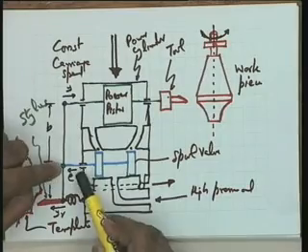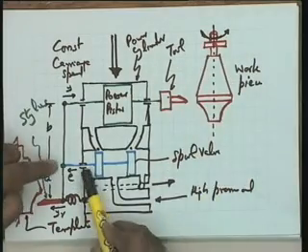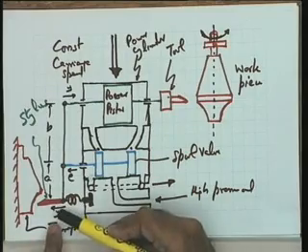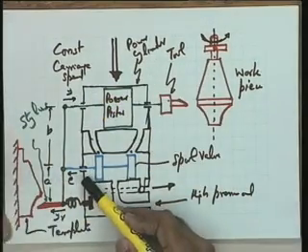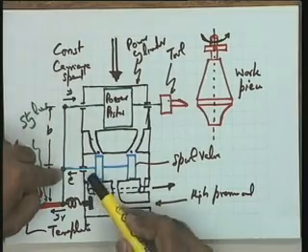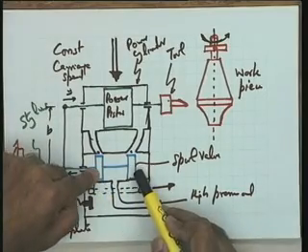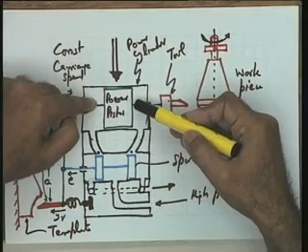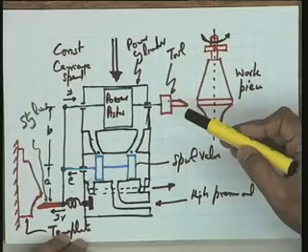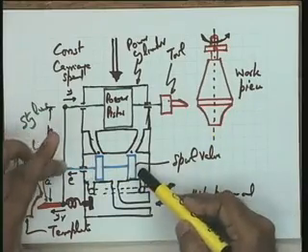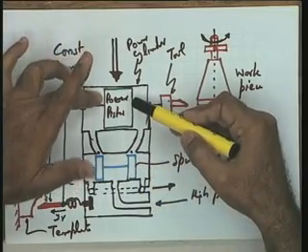Before I give you the block diagram, you should be able to do it yourself now. See the action again. The error E, let us follow the total signals. The error E has been generated on the basis of the reference signal yr and the feedback signal y. This error, what is the action? You recall the equation, depending upon the movement of the spool and the pressure difference del P across the piston, there is going to be a fluid flow. Recall the equation.